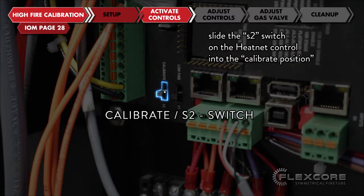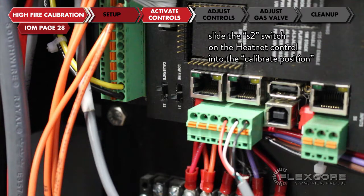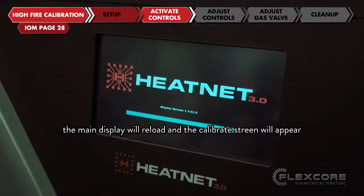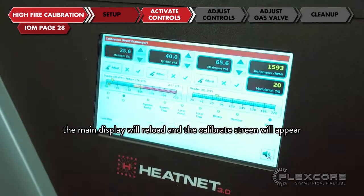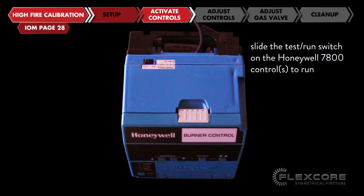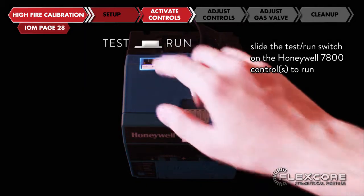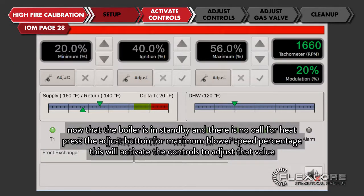Slide the S2 switch on the heat net control into the calibrate position. Main display will reload and the calibrate screen will appear. Slide the test run switch on the Honeywell 7800 control or controls to run. Now that the boiler is in standby and there is no call for heat, press the adjust button for maximum blower speed percentage. This will activate the controls to adjust that value.